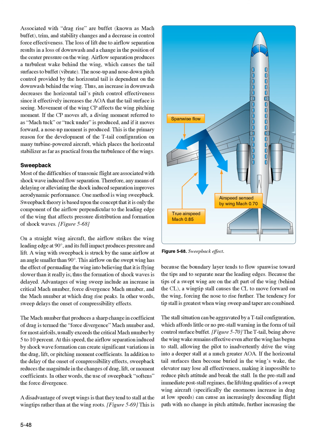Movement of the wing CP affects the wing pitching moment. If the CP moves aft, a diving moment referred to as Mach tuck or tuck under is produced, and if it moves forward, a nose up moment is produced. This is the primary reason for the development of the T-tail configuration on many turbine-powered aircraft, which places the horizontal stabilizer as far as practical from the turbulence of the wings.